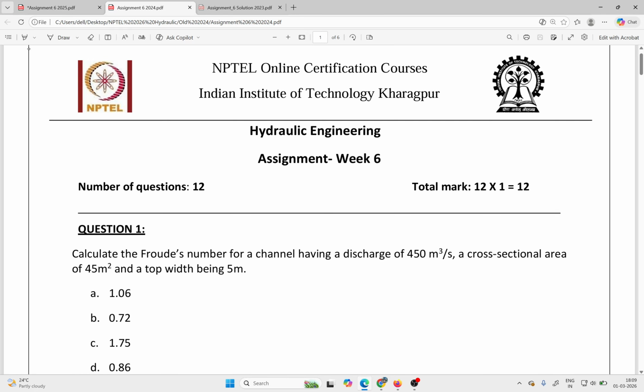Question is, let me just select the pen. Calculate the Froude number for a channel having discharge 450 meter cube per second, a cross-sectional area of 45 meter square, and top width B. Option A 1.06, option B 0.72, option C 1.75, option D 0.86.